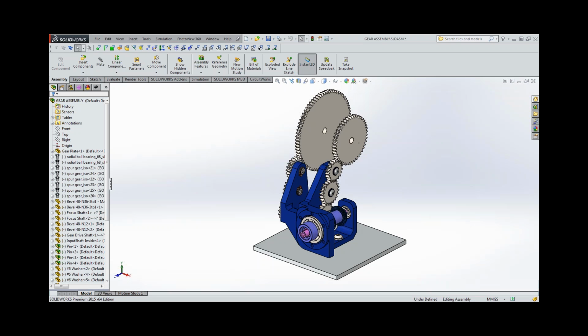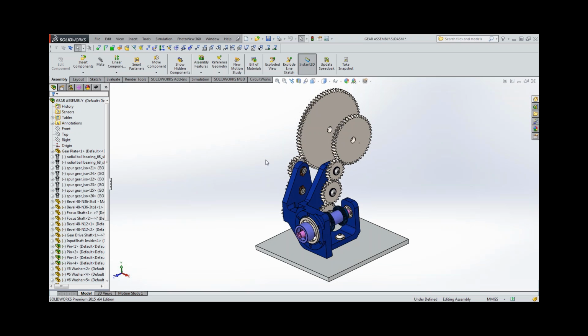easier to understand. In an assembly like this, which is an underwater camera housing where precise fits are required to prevent water ingress, and where these gears need to mesh accurately to control the zoom and focus, every part needs to be machined to very tight tolerances. This can mean high cost, but carefully considering geometric dimensioning and tolerancing can actually lower cost in some cases. So GD&T is not just for close tolerance parts and assemblies, it can be applied to any part.